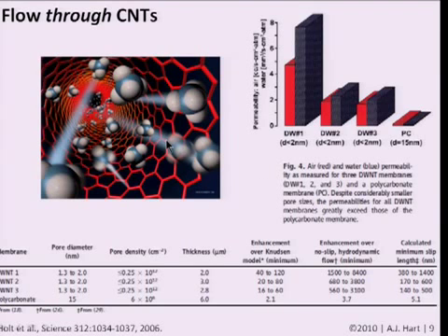And so this is a plot comparing the permeability of the nanotubes, and here they're doing experiments both for air and for water, and it turns out that in addition to the hydrophobicity, because of the smoothness of the walls, there is also very low friction to a lot of things, although water is possibly an outstanding example of something that has extremely low friction.